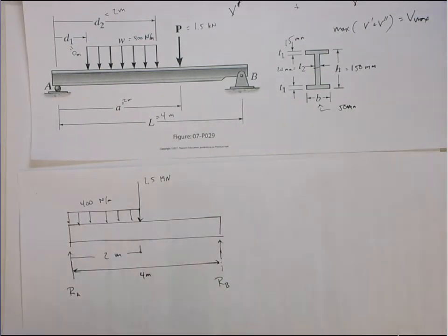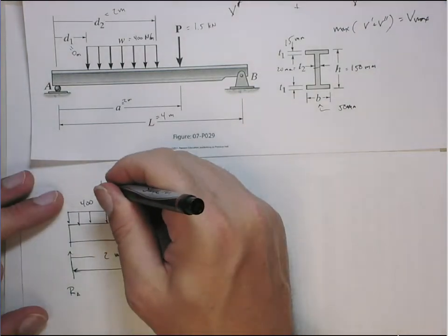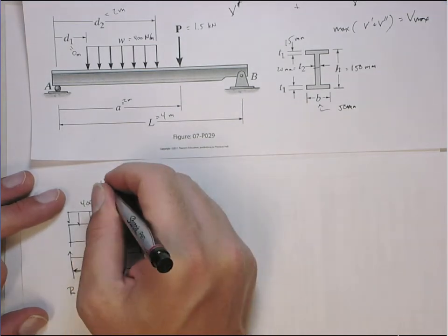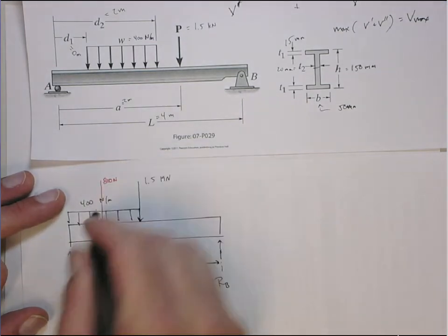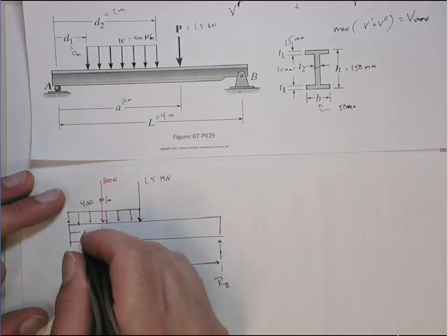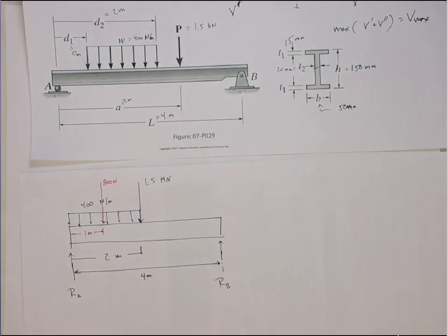All right. So this one has an effective down force of 800 newtons. That's the 400 newtons per meter over 2 meters, and its location is going to be 1 meter from the edge, right? So we can treat it like this to do the equilibrium for the whole body, to get the reaction forces.